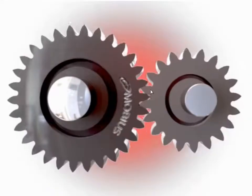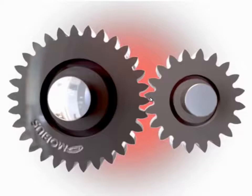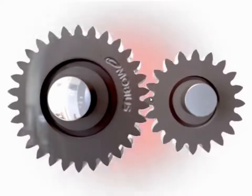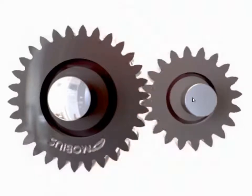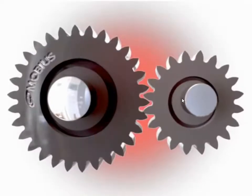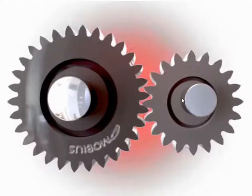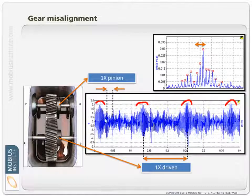Here we have two gears, and if you look closely, they're moving closer together, further apart. Now it's all exaggerated, but if you look at this, it's eccentric. Could be misaligned, it could be bent. We see this pattern. Well, when we look at it as a time waveform, there it is. That's when they're closer together, and in between is when they're further apart. We get this pulsation of vibration.